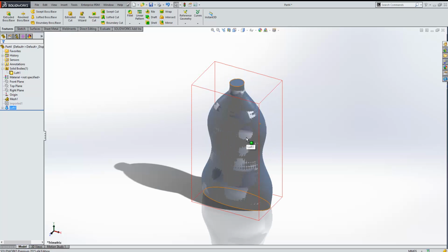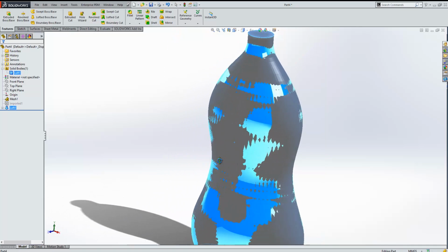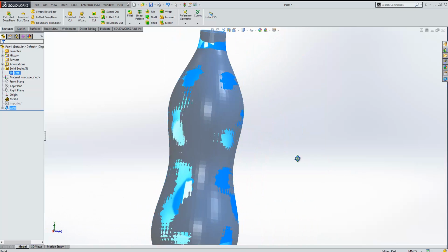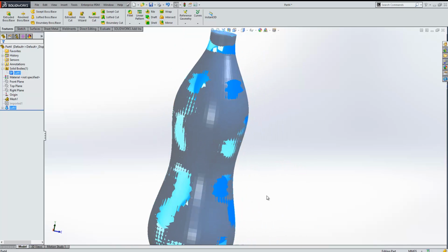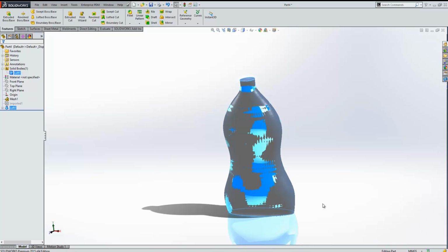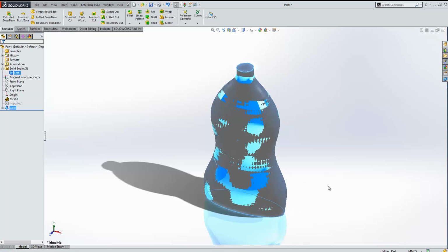Now obviously we've got a bit more control over this than the automatic surface, because we can start to change our sketches around. And if I select it, you can see how close I've got, seeing where things bleed through and where things don't. So you can see the edges are less good than the central section. Again, we get very quickly to a solid where we can start to use our standard SolidWorks functionality. So that is taking meshes, bringing them in, and getting them to the point where we can do something with them, because when they're just a mesh file, there's not a lot you can do. So now I'm going to move on to the direct editing side of things and look at the different functionality.